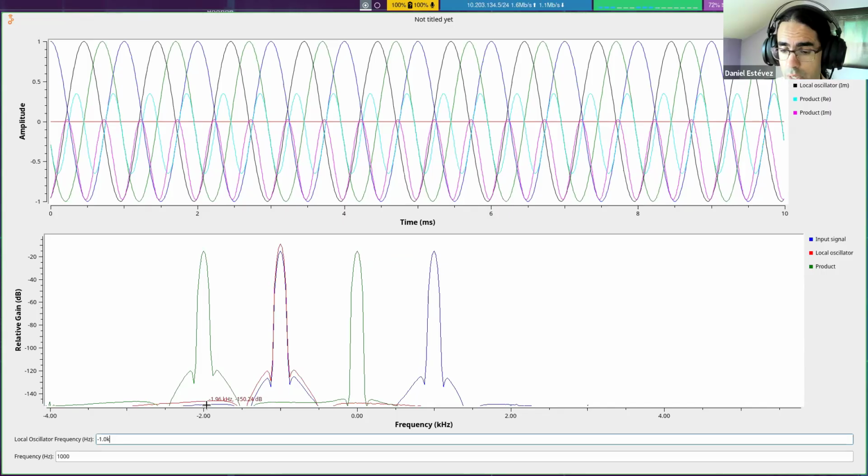So as before, what we can do is apply a filter. As I mentioned before, we will learn how to build filters in another tutorial, and the filter will only let this signal go through. And this is actually how the RTL-SDR works. The signals from the antenna would be the blue thing in here. The red thing is that local oscillator, which is generated on the receiver.